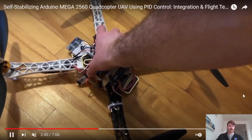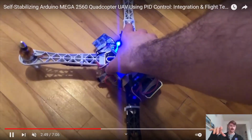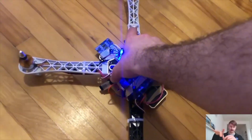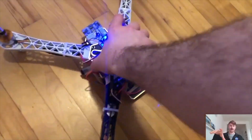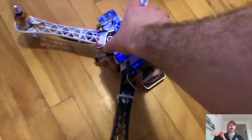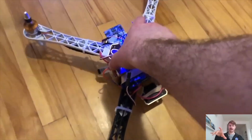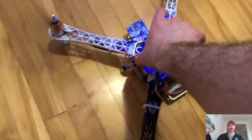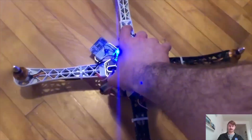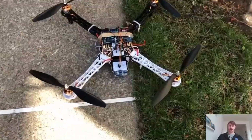So this was after all of the PID gain values had been calibrated, and you see my hand there, and this is actually not holding the UAV, it's more just like a guide. My fingers are just very, very close to it. So this is all flying, doing its own control, and essentially I'm inside testing just to make sure the gain values were right. And my hand was there just to make sure there wasn't any overcorrection and it got away from me. But essentially, it was doing its full correcting algorithm on its own.